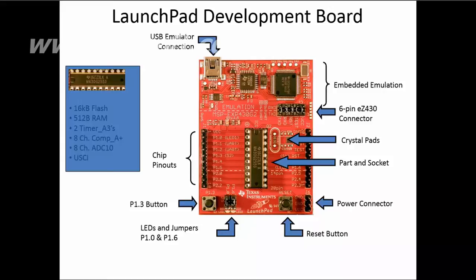RST here is reset. Reset is an active low reset signal. Active low means that it remains high near VCC for normal operation and it is brought low near VSS to reset the chip. Alternative notations to show the active low nature are RST with a bar over it. And we have NMI. NMI is the non-maskable interrupt input, which allows an external signal to interrupt the normal operation of the program.